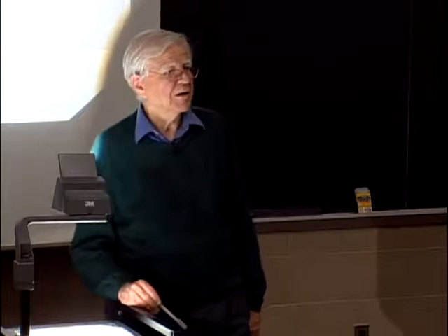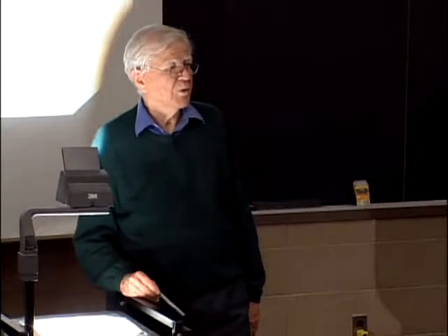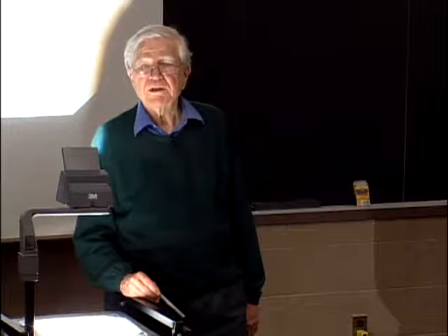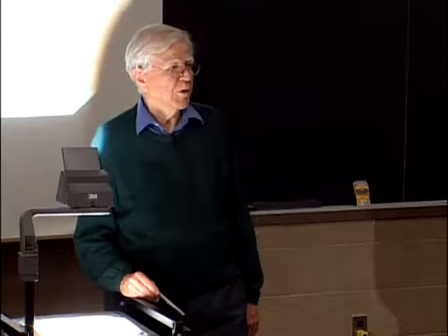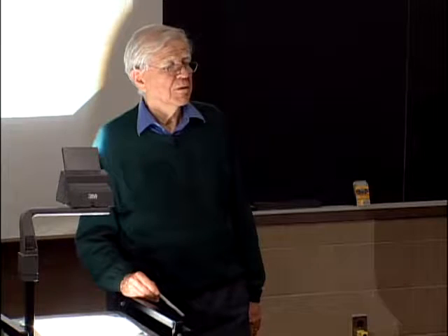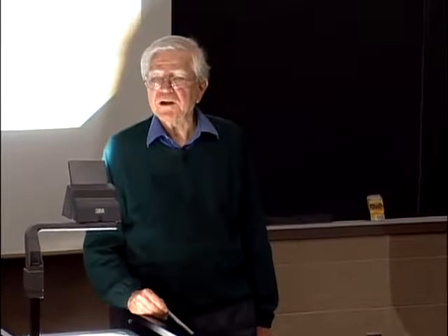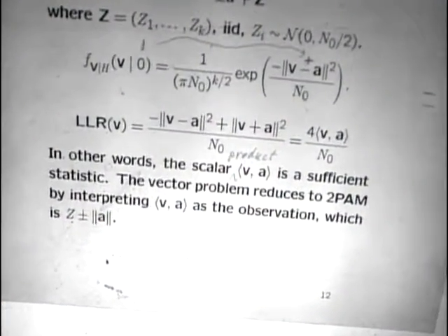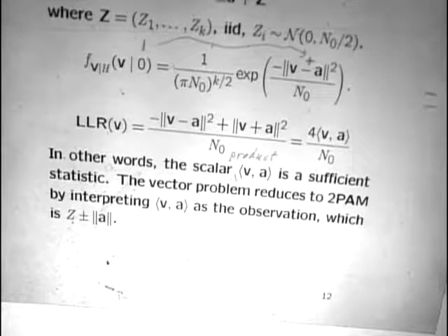What's the inner product for L2 waveforms? It's the integral of the product of the waveforms. And how do you form the integral of the product of the waveforms? You take this waveform here, you turn it around, and you call it a matched filter to A, and you take the received waveform, you pass it through the matched filter for A, and you look at the output for it.